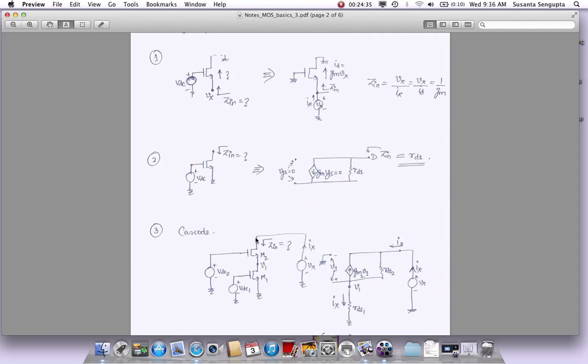That is the beauty of cascode, it boosts the output impedance, and it also acts as a shock absorber, so that the current which is really generated here because of its VGS and the VDS here, that VDS does not change much, and it helps with a very, very constant current. And that's how this technique, cascoding, is used significantly to generate very, very stable current sources.